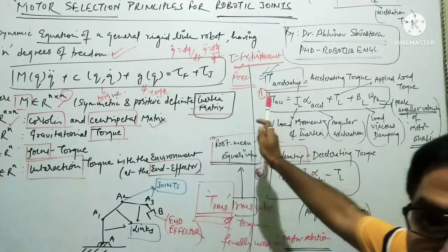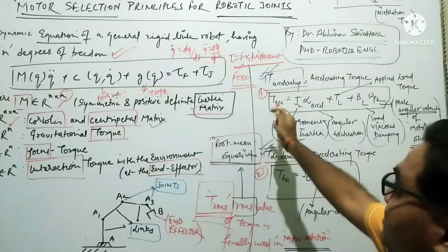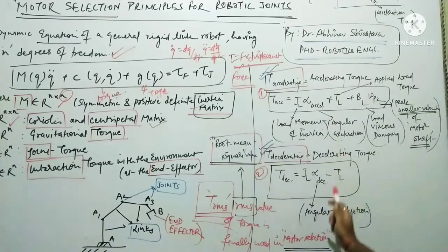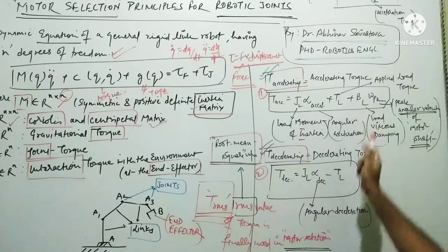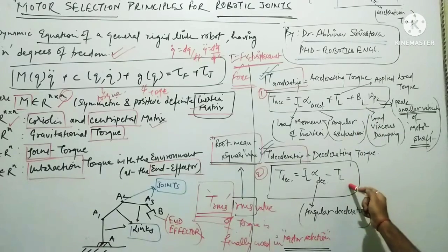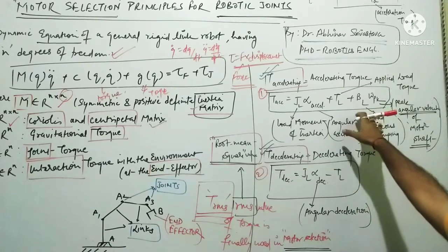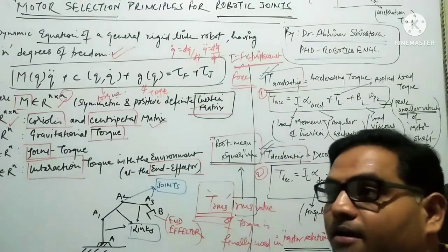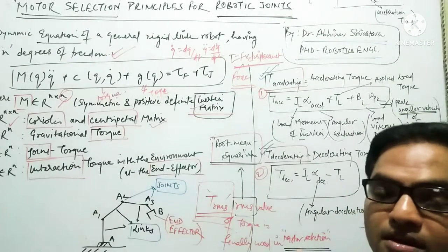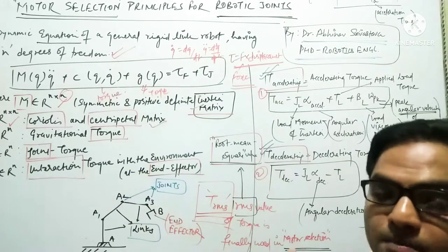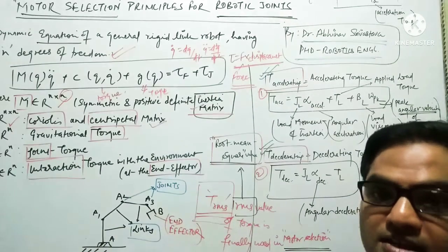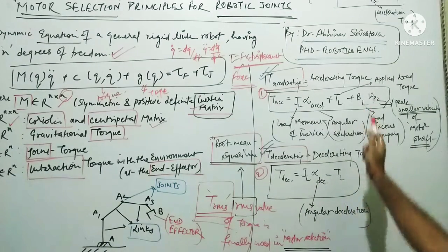The main thing, summarizing a little early: if we compare the acceleration and deceleration torques, all terms are the same except that BL omega pk has not been taken in the deceleration. Why has that not been taken there? Because viscous damping already supports the deceleration torque, as these forces are negation forces. When we decelerate with certain torque parameters, viscous damping is already there and supports it. That's why we have not included it here.